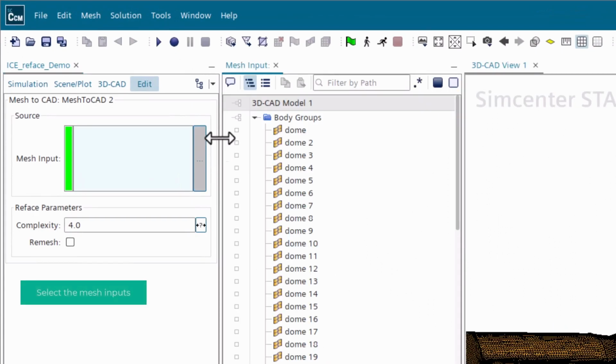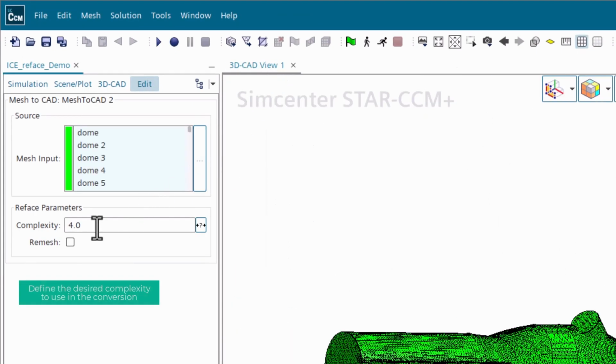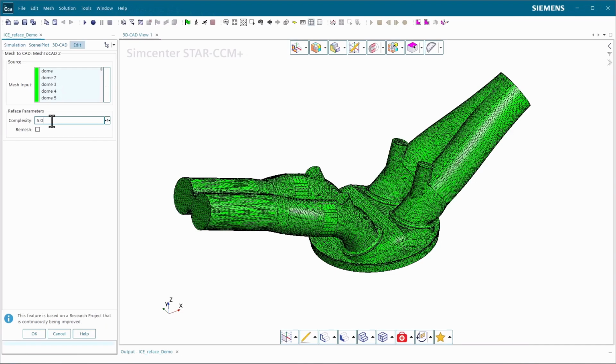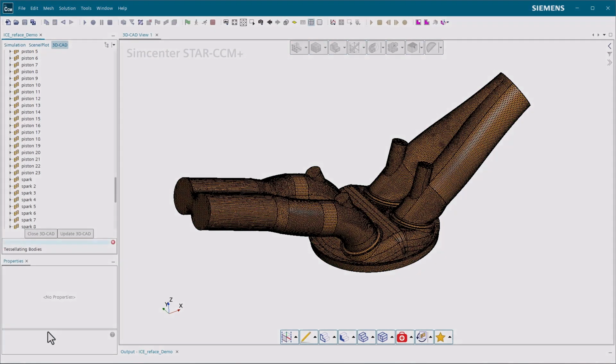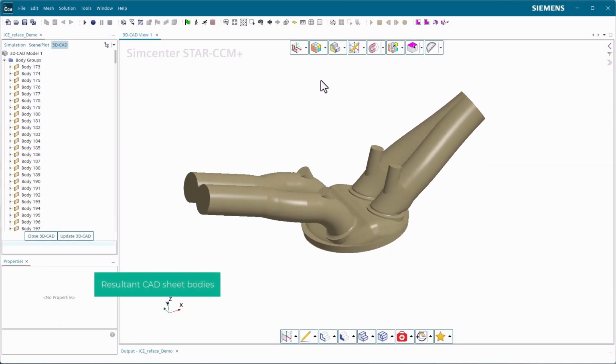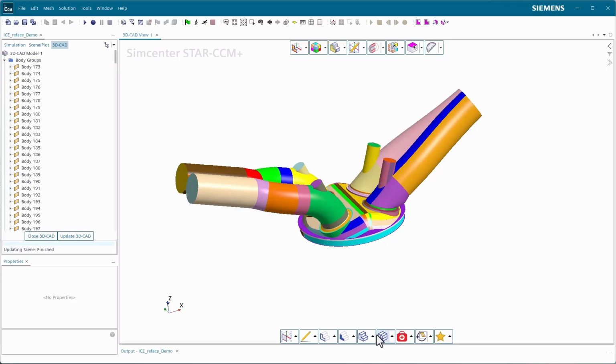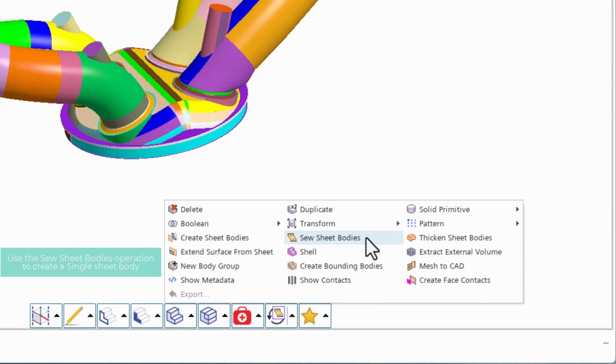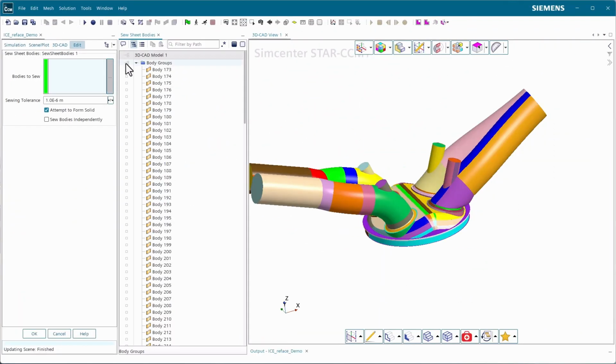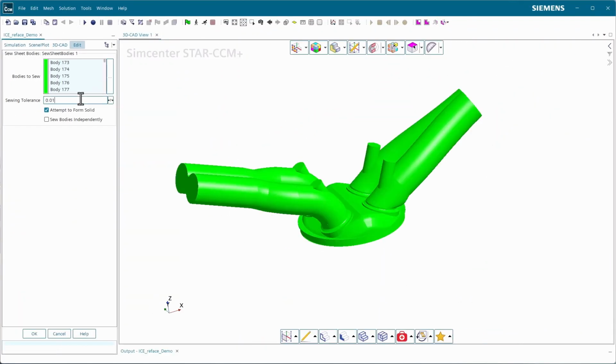And relying on the tessellated geometry, the analyst is not able to perform the necessary defeaturing and removal of those elements in the geometry. This is where, by converting to a CAD body, the user is able to defeature the geometry of those elements for the analysis, and also, to extend that, have the ability to parameterize the geometry for design studies and do more exploration of the design space that way.